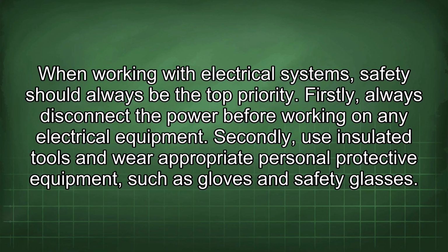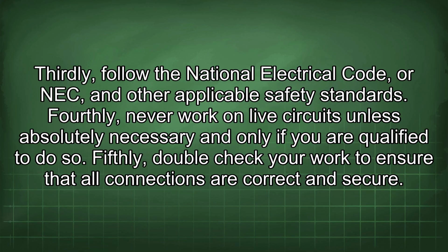Firstly, always disconnect the power before working on any electrical equipment. Secondly, use insulated tools and wear appropriate personal protective equipment, such as gloves and safety glasses. Thirdly, follow the National Electrical Code, or NEC, and other applicable safety standards.